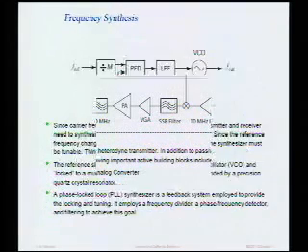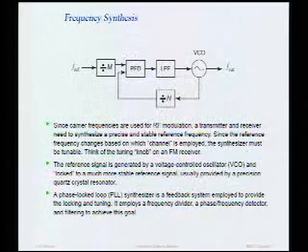Let me just say a couple more words about the frequency synthesizer. In this course, we're going to spend a lot of time building oscillators. We're going to learn how to build oscillators inside and out. Most of the oscillators we build will be LC oscillators, if you're familiar with that term. We also will touch upon how you build a frequency synthesizer. In particular, we'll look at how you build a frequency divider, how you build a phase detector or phase frequency detector, and basically this is a low-pass filter.